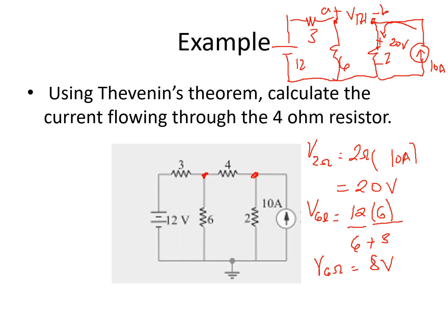So what is the polarity? The polarity is minus plus. It will flow here. So this is plus, this is minus, and we have here 8 volts. Okay? So if we're now going to have our loop here, following the loop, we have here positive 6.